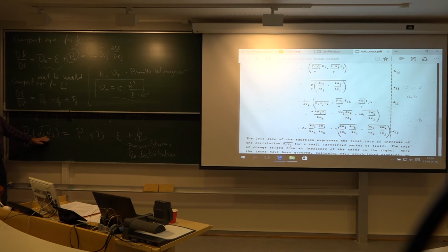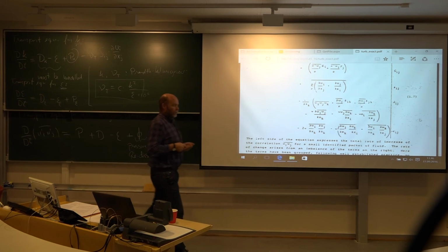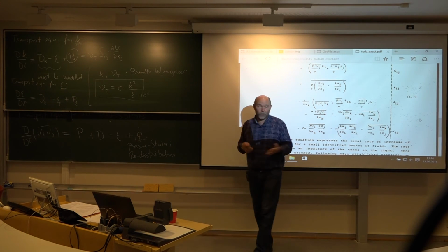So it is a redistribution of energy among the unknown functions. And clearly now we have gotten a sense of direction, opposite to the K epsilon, K omega two equation models, which have no sense of direction whatsoever. But here you will have components for each direction, u square, v square, and so on. So this model is much more advanced, and can cover much more physics.